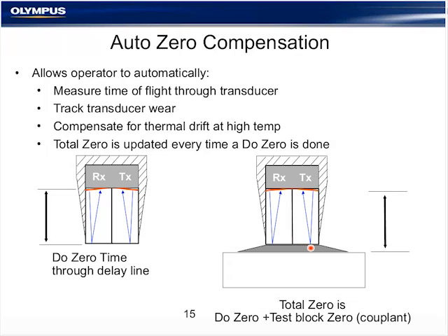Now, of course, it doesn't include the couplant layer, and it doesn't take into effect any surface roughness conditions, but it's quite a large step towards accurate measurements compared to starting from an actual initial pulse zero and having to make a full calibration in order to eliminate any probe delay from the measurement. So this is a really important component of simplifying the setup of a corrosion gauge.